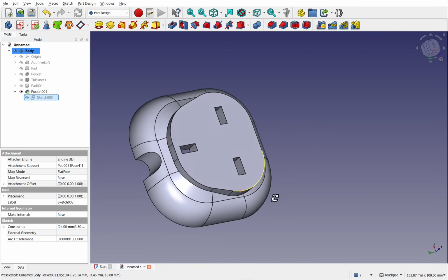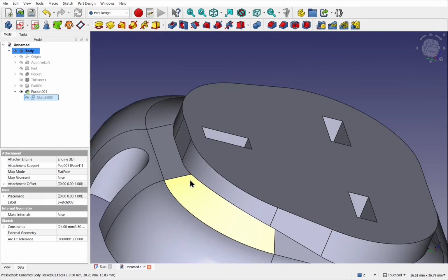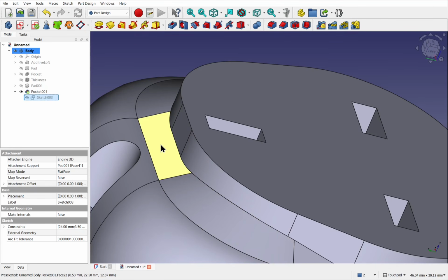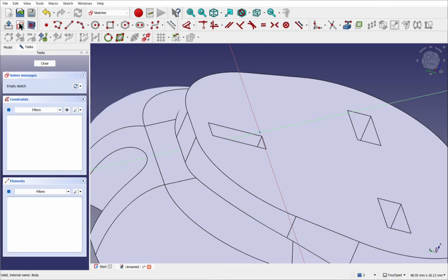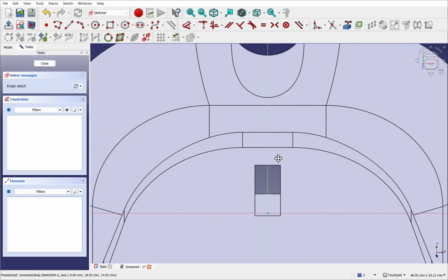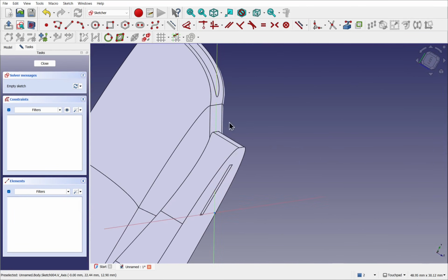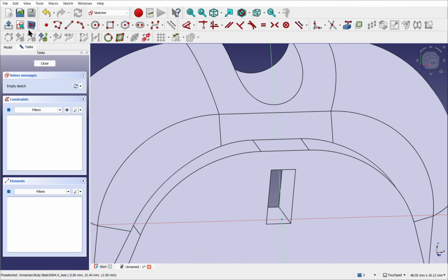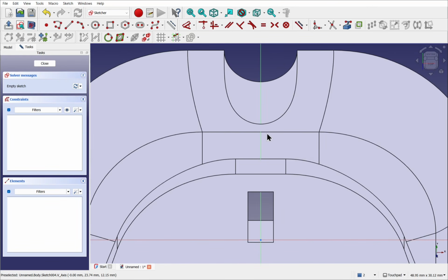We've got one final piece of geometry to add, and that's the ventilation holes. Now we can see that this is a planar face, so we can just select it and sketch upon it. We're upon that face now, so you can see it there. Let's just use View Sketch to view that from the top. Let's learn a new tool, and that's this tool here, the Move/Array Transformation. This allows us to create some geometry and array that across here.